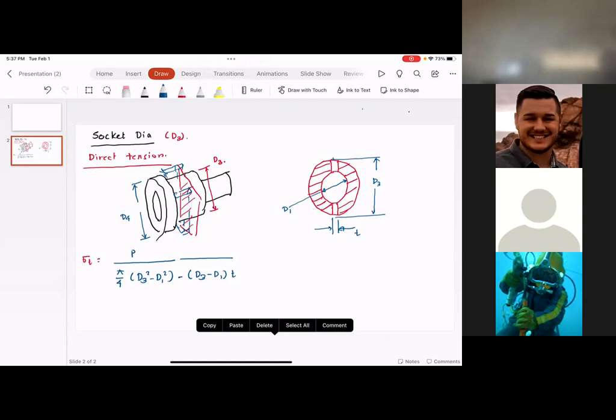Okay. Yeah. Because when I checked it for bending, when I went through it the first time, I used D3 instead of D4. And I could have done it wrong, but I thought that it failed in bending. What would we do in that case? So now here is what happens. Almost always, you would notice the cotter would fail in bending. And there is a reason for that.